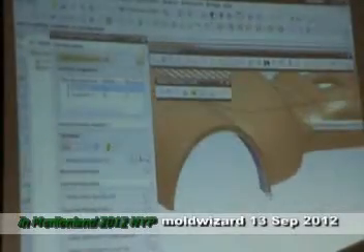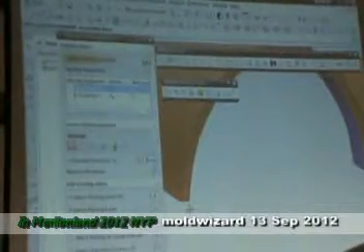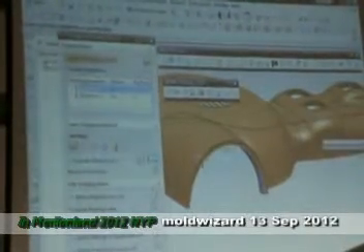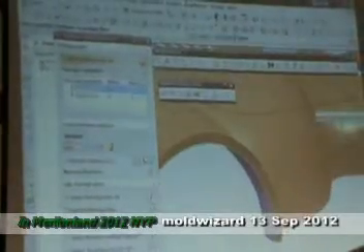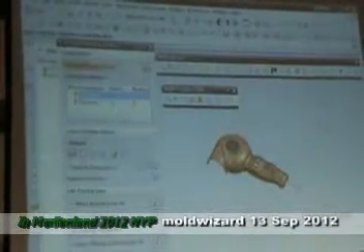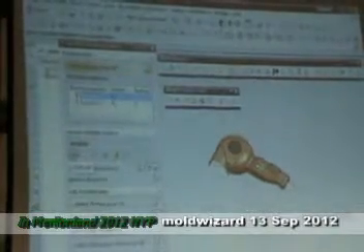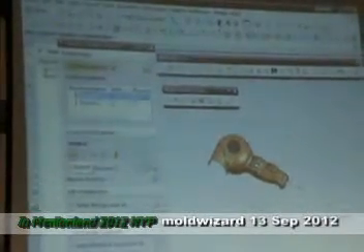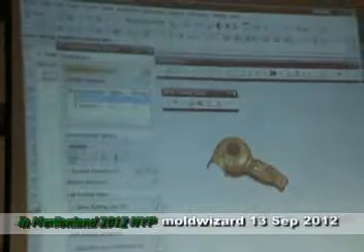You can see the colors have changed. The planar face is red, and the transition curves are light green. Now the software will choose extrude for everything.